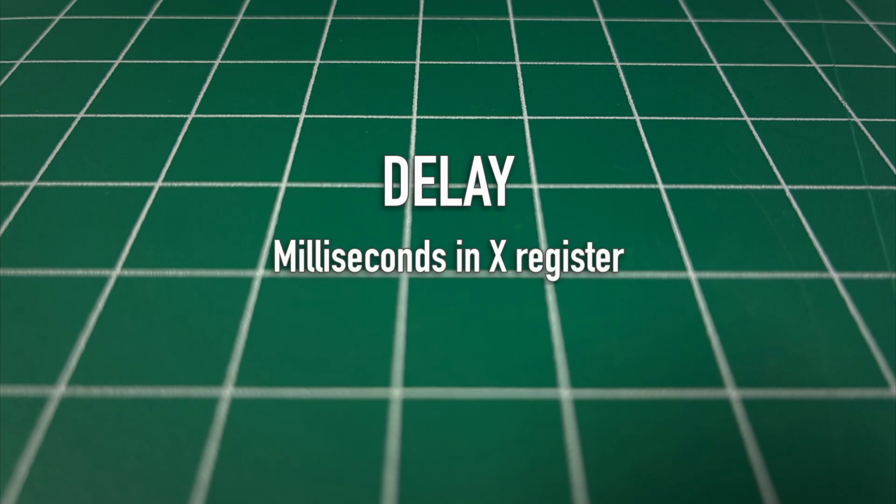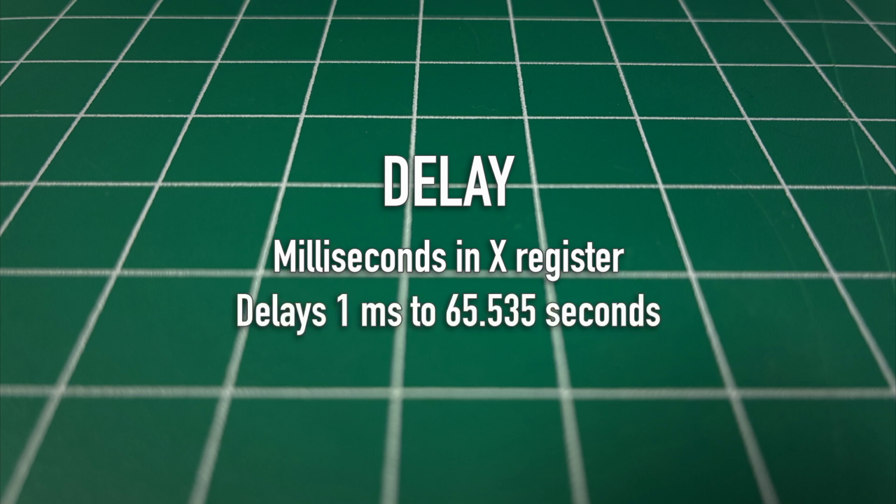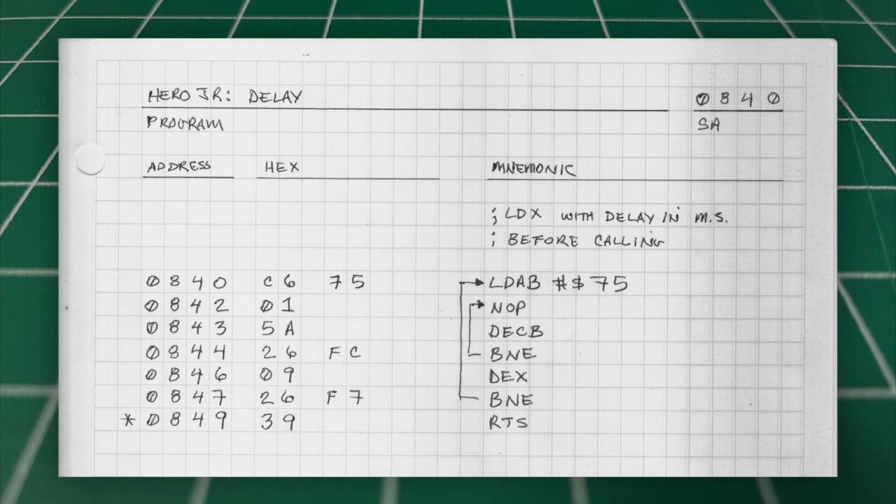If we use the X register to hold the number of milliseconds we want to delay, then we can wait up to 65,535 milliseconds, or just over 65 seconds. That sounds about right as a maximum wait time. If we need something longer, we can always call it twice. Here's the listing. It's surprisingly short.